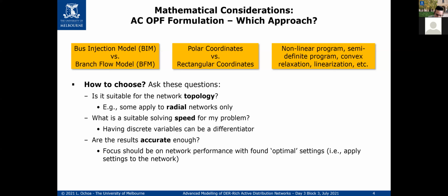And how accurate your results need to be as well. That accuracy will depend on the nature of your problem. So if we're talking about, for instance, voltages, the reality today is that voltages at our homes, forget about renewables, forget about photovoltaics, were already all over the place, all right? I know that, for sure, for many years. Our voltages in many places are sometimes a little bit outside the limits, but we don't complain because our devices at home today are pretty robust with respect to voltages. It's not like the old TVs where with lower voltages the image would go smaller, or you could see issues with your incandescent light bulbs. And then, of course, the voltage reduces, the light reduced.